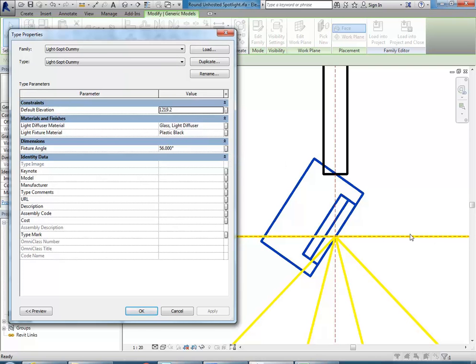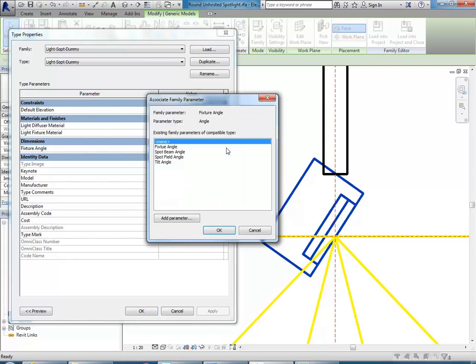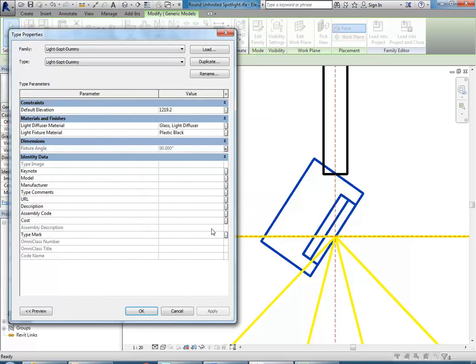So it's, is it plus minus 90, I think it is. So I'm going to click on this one, and I'll add in a new parameter to this file. Well, or I can use fixture angle, which is the fixture angle parameter I've made in this file. So I'm plugging the parameters from this family into the ones in the file that I've loaded it into.